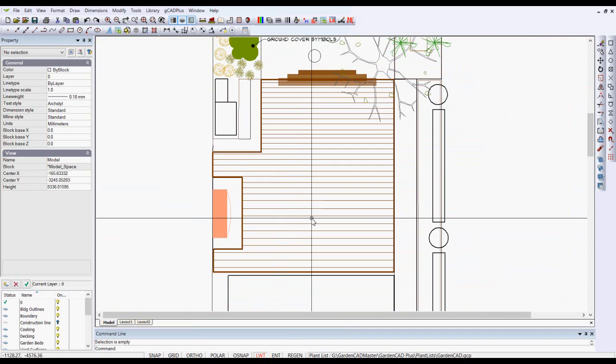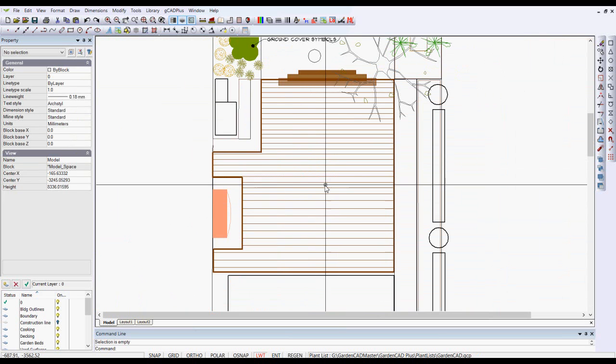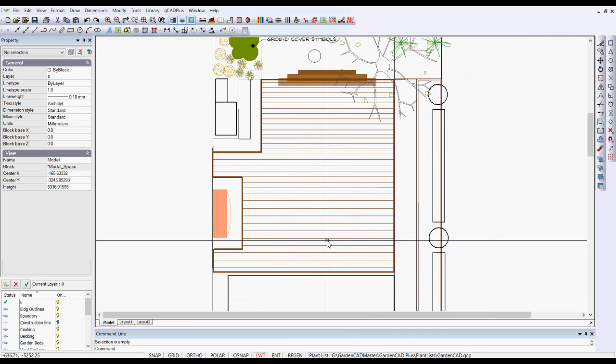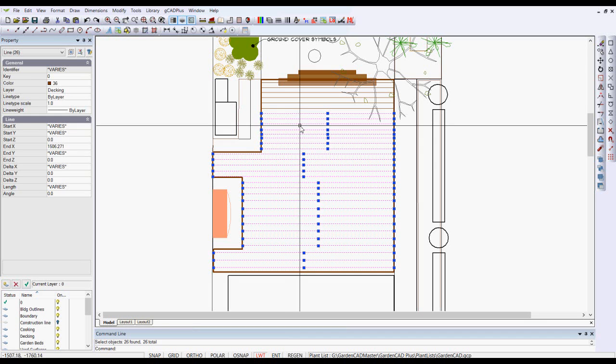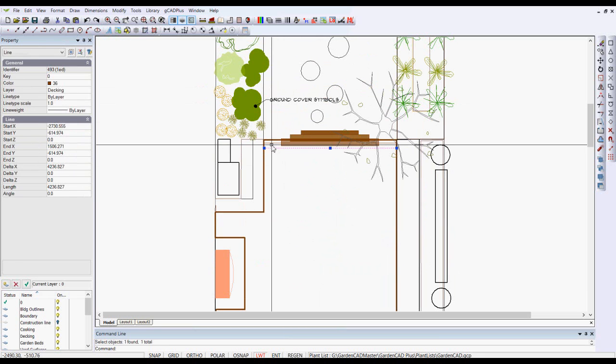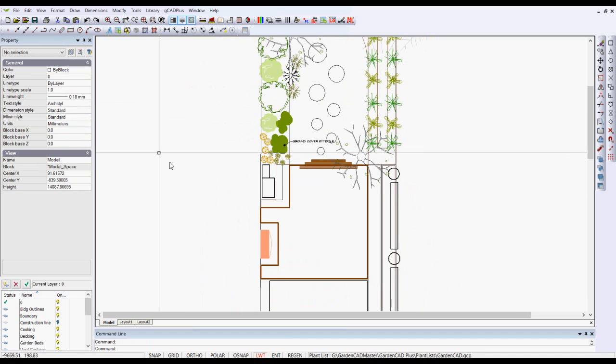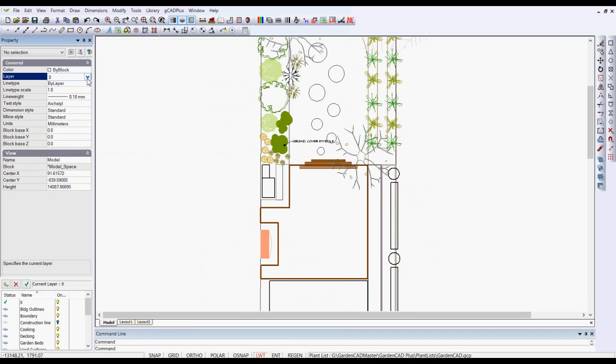So I imagine then that what he's done is to apply a hatch pattern to that zone. So I'll just select, that what's been done here is individual lines are put in there. So I'd be inclined now to remove those lines like so. We've got a couple more to remove, and I'll just check my current settings. My current settings are that I'm on a layer called 0. Let's set a decking layer, so now whatever I draw will be on the decking layer.